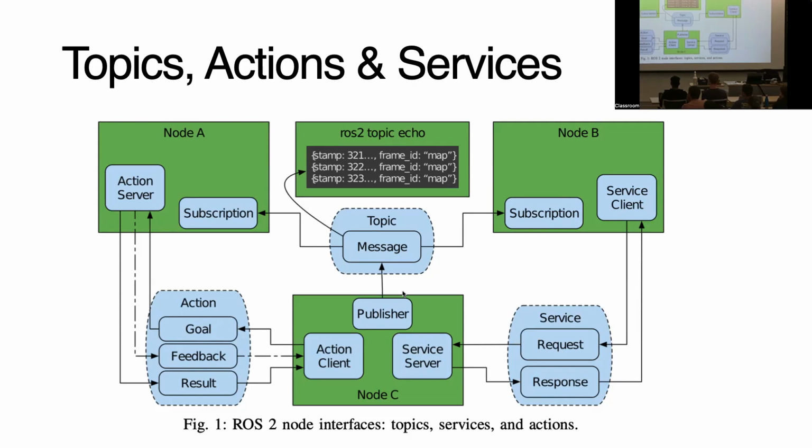So a message is just a message. It's just data that gets sent on a topic. A service has a request and then a response. So instead of sending messages with joint states, you could set it up where you requested the current joint states and the service would respond with whatever the current joint states are. We might be using a service for turning on and off the torque of the motor, but it's transparent to you. You don't have to worry about it.